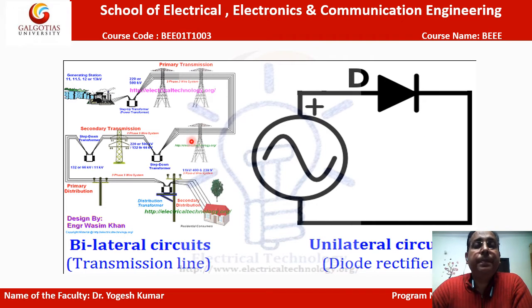Here you can see the photos of the unilateral and the bilateral circuit. For the unilateral circuit, I already told you the diode is the best example. It will allow the flow of current in one direction only. It has such a symbol. The triangle shows the p-type semiconductor material and the bar shows the n-type semiconductor material. So it allows the flow of current in the forward bias, in this clockwise direction. In the reverse bias, it will not allow current to flow in the back direction. And this is the figure given for the transmission line circuit. It acts as a bilateral circuit.